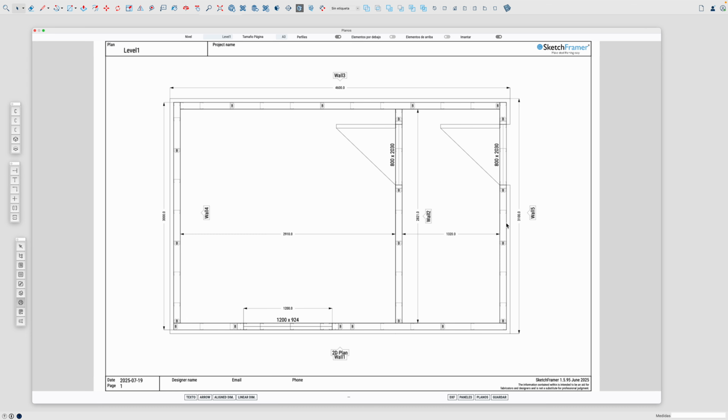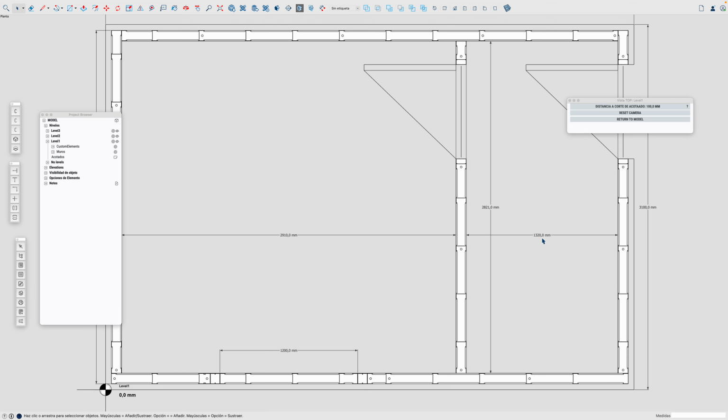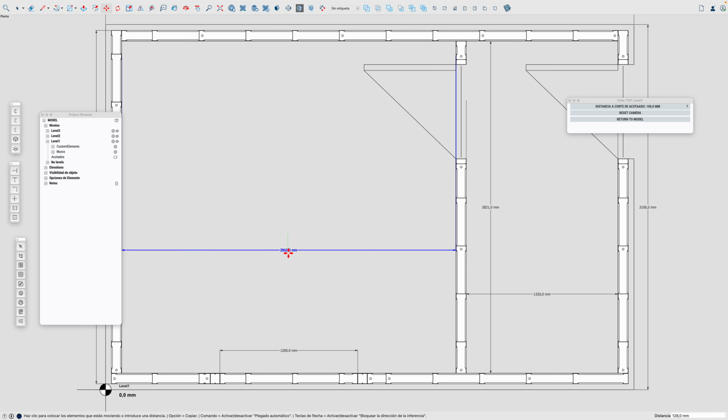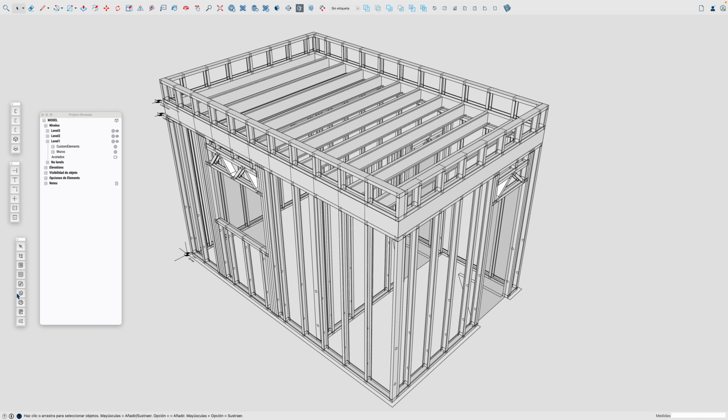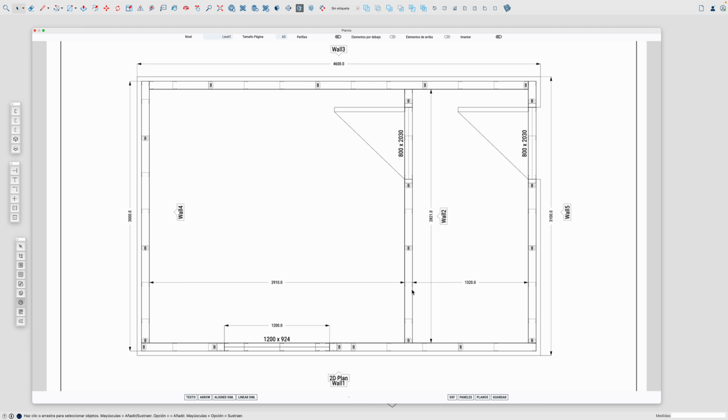But to set the placement of the dimension, I should go again into the dimension space. Let's hit save. Remember this position. Let's close this, go to our dimension space and move this here and let's move this here. Return to model, return to printing space, and you see we modified the placement.